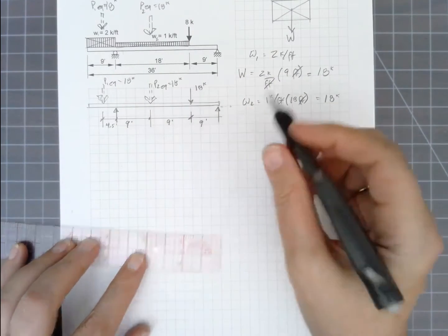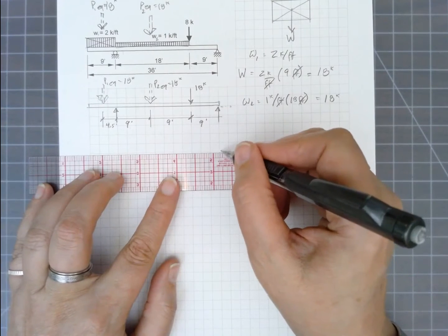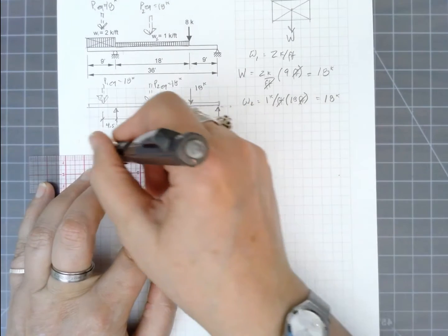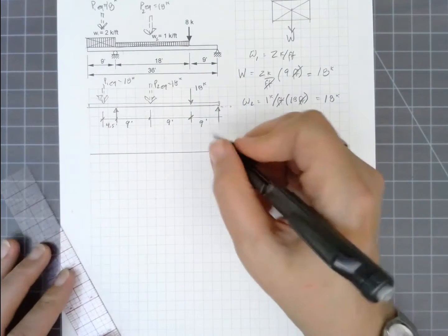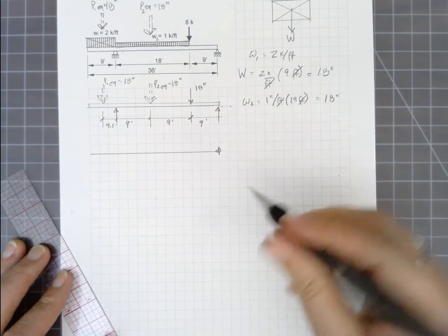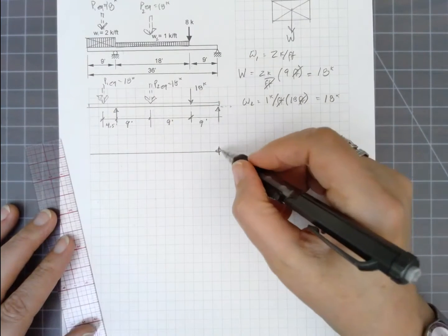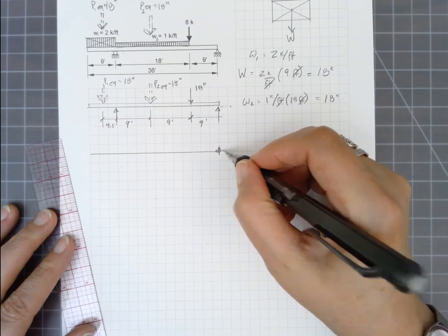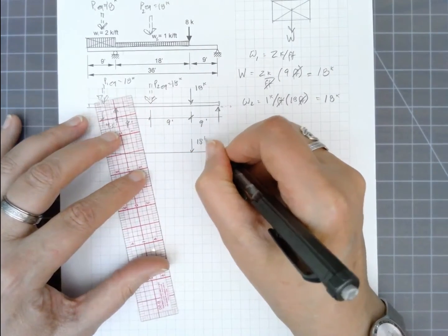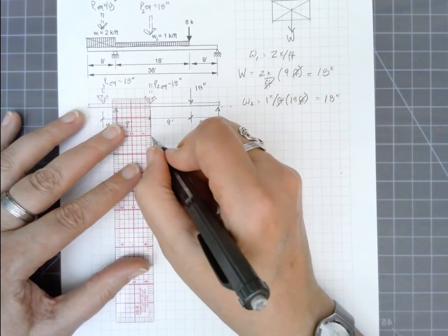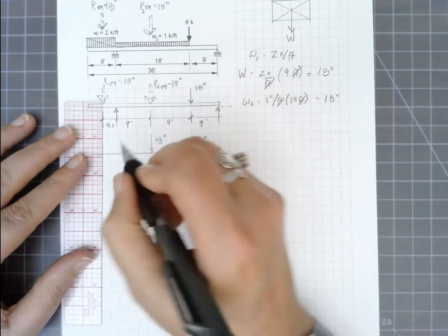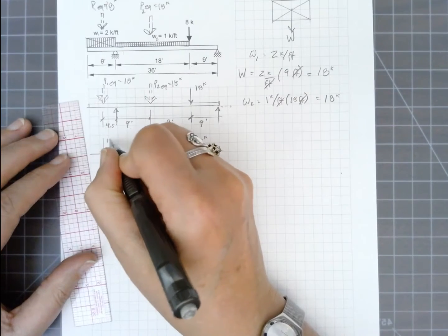So I'm going to set this up and redraw this yet again, because I need to use my rotational equilibrium equation. And I want to look at this starting off on the right-hand side here. Look at all the loads that have a tendency to rotate relative to this point here. So it's against the 18 kips here. And just for simplicity, I'll just draw that as an arrow. This is 18 kips. This is 18 kips.